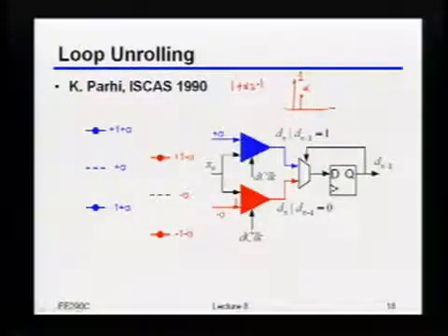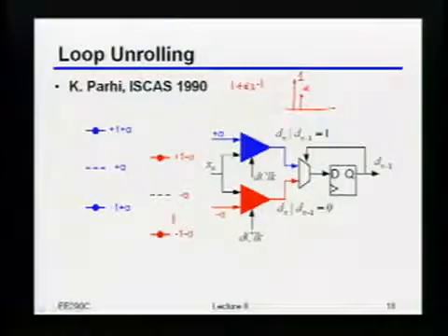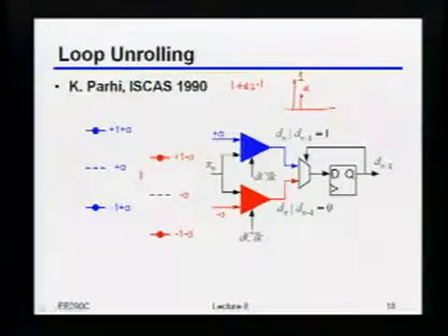Okay, so I wanted to spend a little bit of time on what these different levels look like, because you'll sometimes see eye diagrams with these loop unrolled DFEs. By the way, in the communication terminology, this is sometimes called a partial response channel, meaning that you're not canceling all of the response, but you're leaving some amount of intentional ISI there that you're just going to deal with later. If you look at the eye diagrams for these things, they tend to look, let's say, funny.